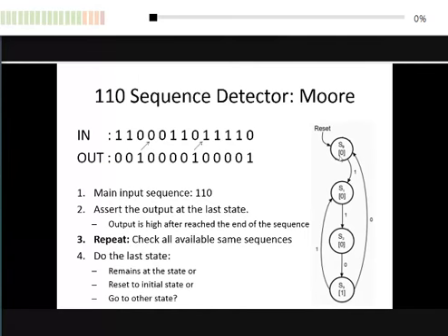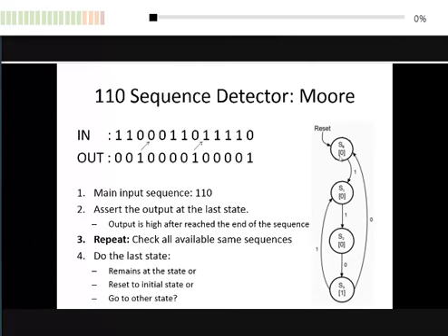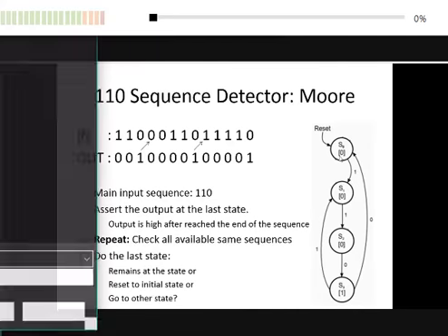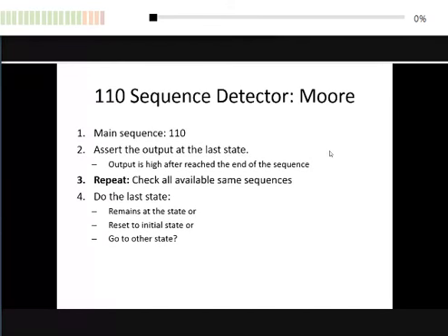Look at S1. You only have an output arc when it is 1. There is no output arc when it is 0. S2, you only have an output arc when it is 0. There is no output arc when it is 1. But S3, we already completed it when we checked the initialization of the sequence. So the only state that is complete is S3. So how to complete the S0, S1, and S2 arcs?